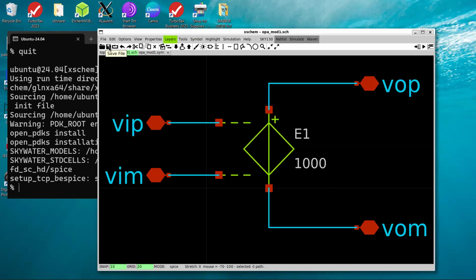Okay. So you put the pin, and this is just the pin name. You can call it obviously whatever you want, but having names which correlate with the functionality makes it easily readable. You can call it VX or NX or your name or whatever it is, but then when you get the symbol, you have no idea what that symbol means.